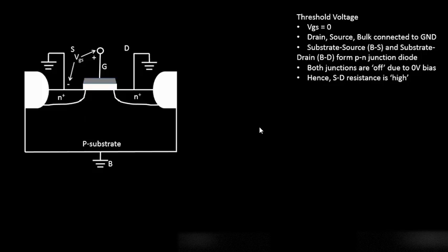Now we'll apply a small positive potential at the gate to source and see what happens. Applying a positive potential essentially means that this metal gate is positively charged. By the way, this is polysilicon, this is the oxide, and this is again the p-type substrate. So this area forms an oxide capacitance: the oxide acts as a dielectric between two metal sheets, which basically forms a capacitance.